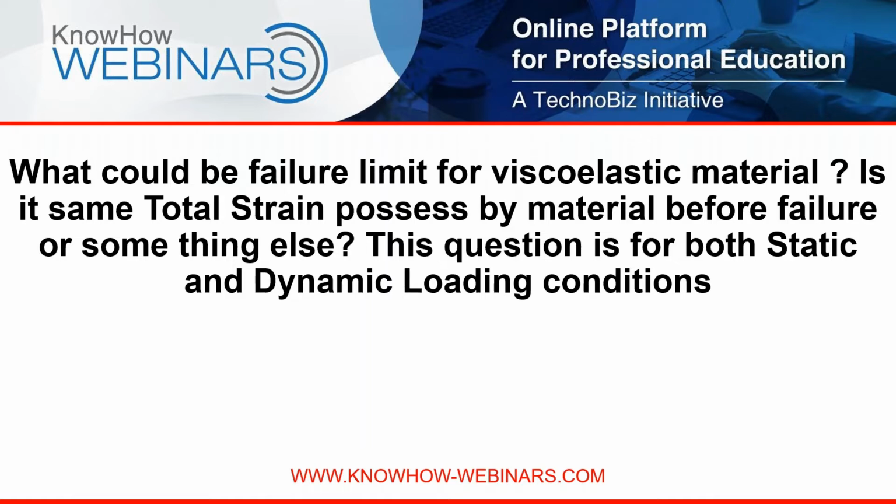What could be the failure limit for a viscoelastic material? Is it the same total strain possessed by a material before failure, or something else? The question is for both static and dynamic loading conditions. See, when you carry out a tensile test on a quasi-static process, say for example, your material fails at 10 megapascal at 1000% strain, right?